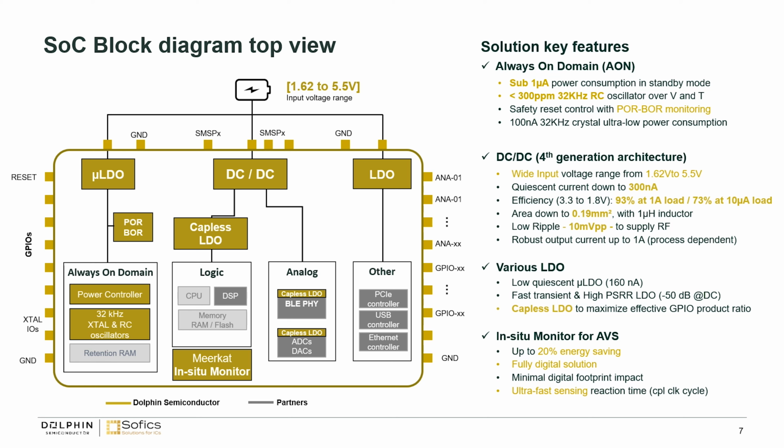Now on the right part of the block diagram, you have this big LDO that can supply all the peripherals that could be power demanding, like PCI controller, USB, Ethernet, and so on. So this LDO, you have plenty of flavors, can support 200, 300, 400 milliamps up to 1 amp, right? Therefore, you can get enough current that you need. And now on the left side of this block diagram, what we see is a micro LDO. What is a micro LDO? It is an LDO that we're going to use to supply and to power what we call in the microcontroller or device the AON, always-on domain.